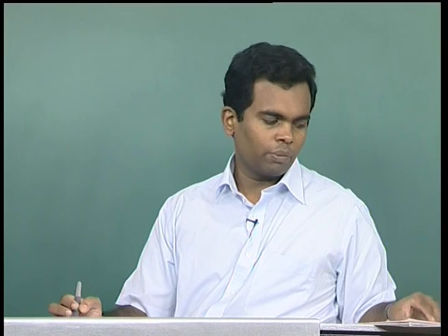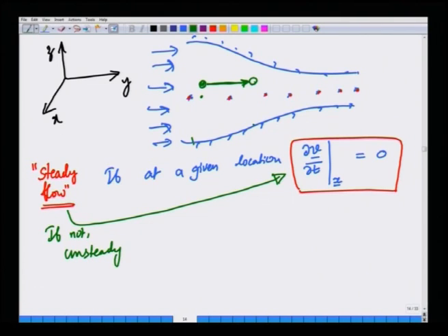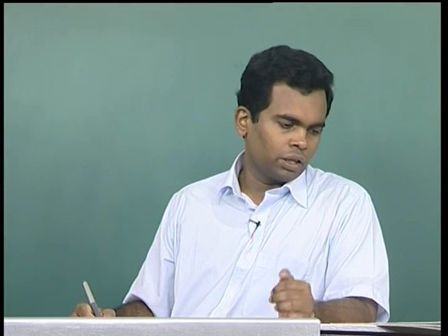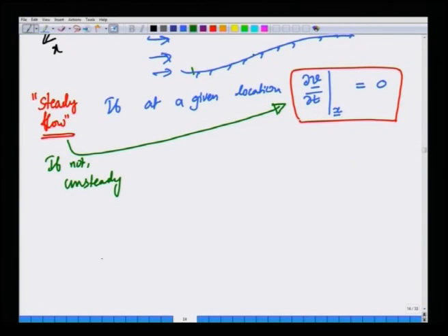But in fluid mechanics, by steady flow we mean that the Eulerian velocity field is independent of time. Otherwise, flows are called unsteady. That is, if velocity is indeed a function of time at various points in space, then the flow is unsteady. People also use the classification 1D, 2D and 3D flows in kinematics.